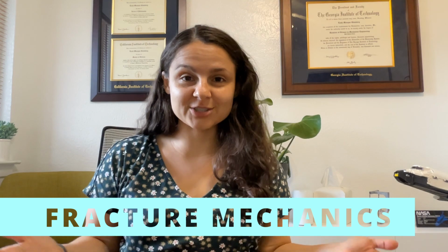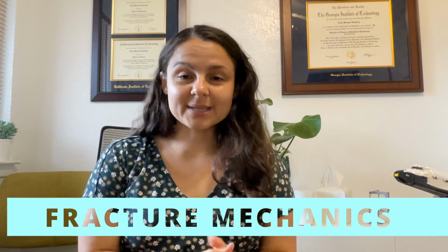Hello, welcome back to our machine design series, where today we are talking about fracture mechanics. Linear elastic fracture mechanics is a theory that we can use to describe a brittle failure mode of both brittle and ductile materials. Keep in mind that so-called ductile materials can still experience this brittle failure mode, and the reason for that is that all materials have these small defects inside.